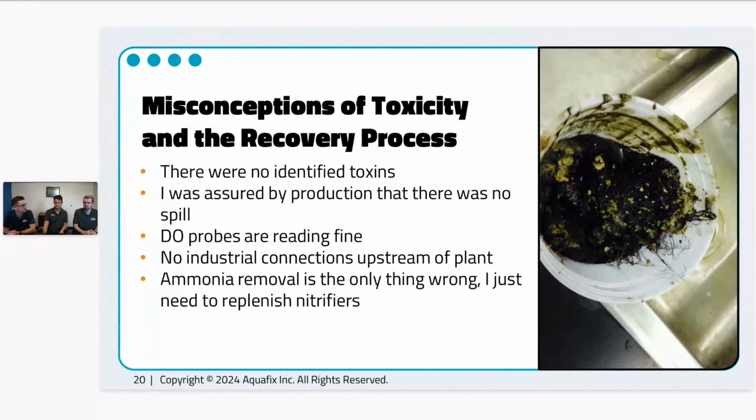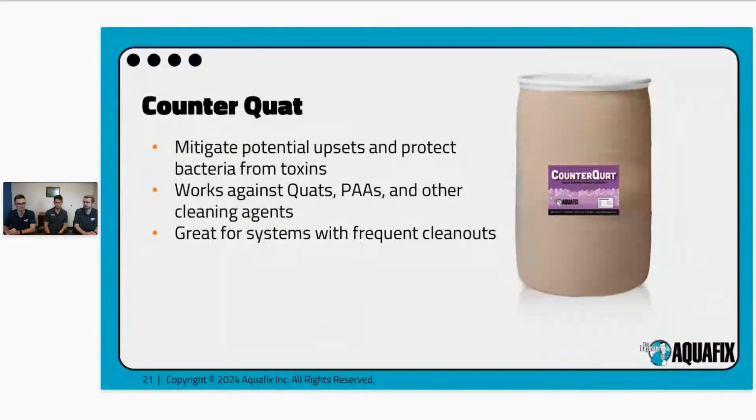Yeah, and kind of on that last point, Tyler, nitrifiers are kind of the most sensitive organisms. So if we're trying to add back ammonia removal and replenish nitrifiers, if the plant still has those stressors in place, the nitrifiers don't necessarily take as well. That's going to continue running issues. The really big thing is remove the stressors, fix the underlying issues of what it is, and then we can start looking at getting those nitrifiers back in, starting with ammonia removal.